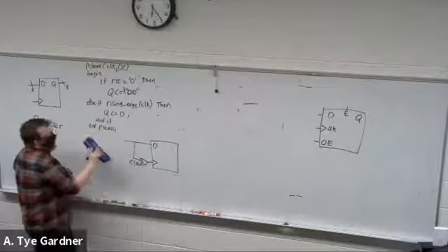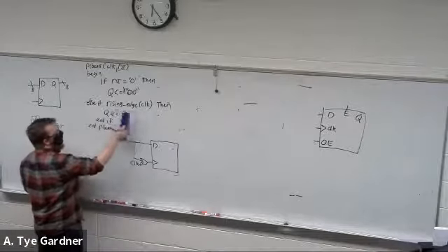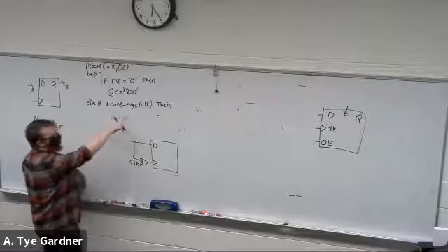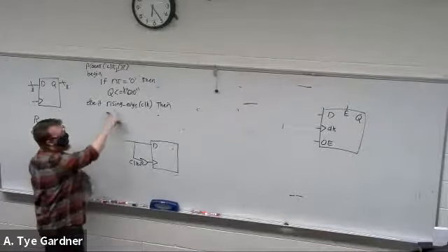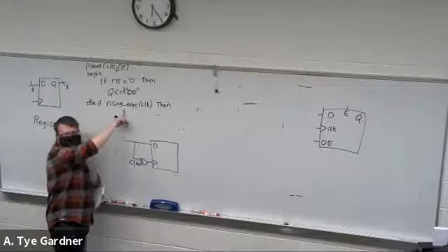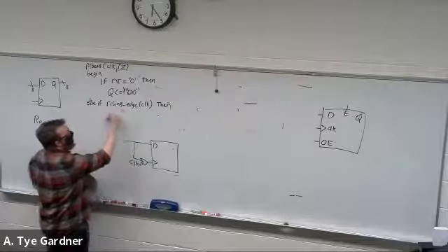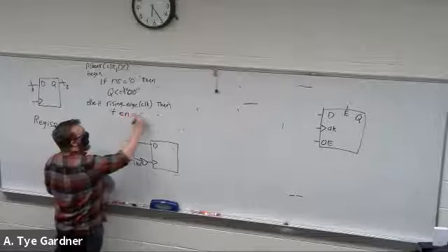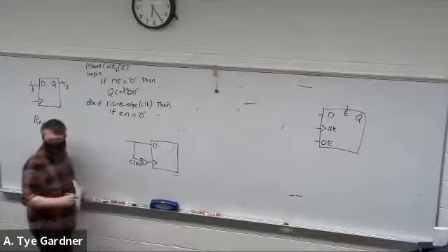An easier way to do it, if you want, it's kind of up to how you guys prefer. I don't really do in VHDL a lot of this and that, especially with the rising edges, because it makes the debugging more difficult because the errors get kind of unclear. So for this purpose, I do kind of recommend doing an embedded if statement.